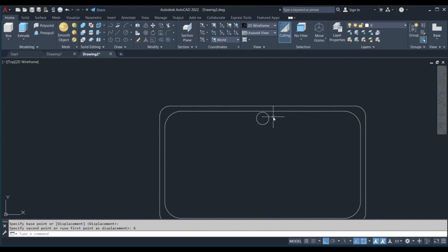So what do we do here? We now want to make the other curves. Now the bigger circle has a radius of 15 centimeters. Let's work on this. The radius is 15 centimeters, and we want to use it to fix here. We need 2 points. We need the tangent.